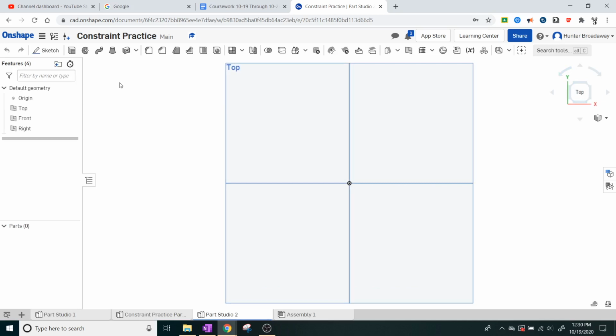Begin a new sketch to create a similar shape using lines and program suggested constraints. Don't worry about line length as you walk through the steps. You will place dimensional constraints later. Place a line on the x-axis, allowing software to suggest a horizontal constraint and automatically constrain the line. I kind of do that all the time anyway.